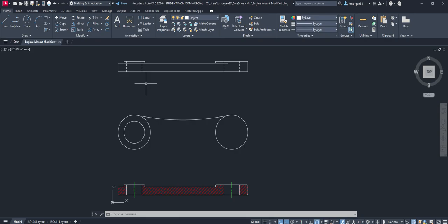Once you finish it, we are going to do a second offsetting. Just go ahead and press Enter to go back into the offset command. This time we are going to enter 13. Type in 13 and then press Enter on your keyboard. Once you finish it, we always pay attention to the changes in the command line.